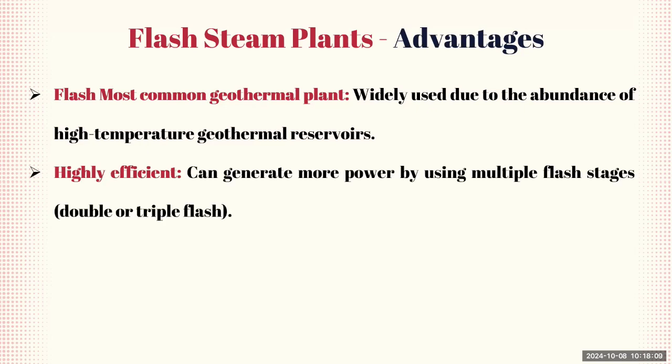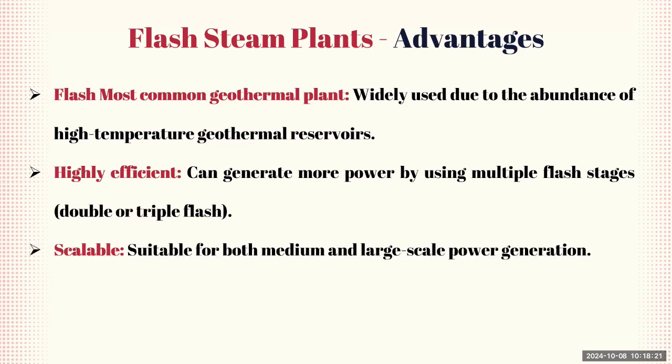Another advantage is that they're highly efficient, so these plants can generate more power by using multiple flash stages, such as double or even triple flash systems to maximize energy extraction. Not only that, they're also scalable, which means that flash steam plants are suitable for both medium and large scale power generation, making them flexible in terms of capacity.